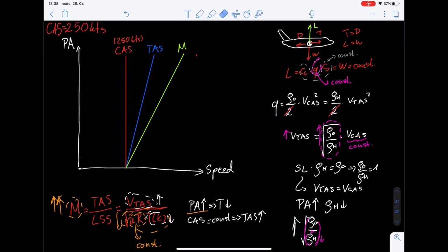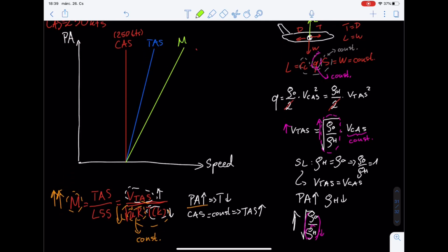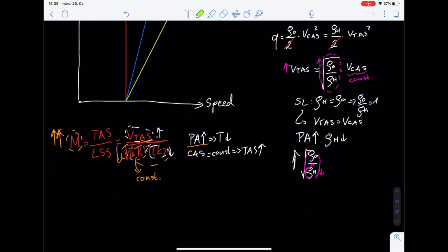You've also covered this fairly in detail in Principles of Flight, but usually there is this critical Mach number where the first part of the aircraft, usually the thickest part of the airfoil, reaches the local speed of sound. And usually that's expressed as the true airspeed of the undisturbed airflow over the local speed of sound. So it's the Mach number, you could say, for the whole aircraft. Therefore this critical Mach number is usually less than 1.